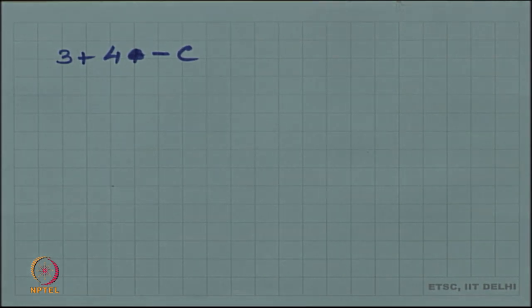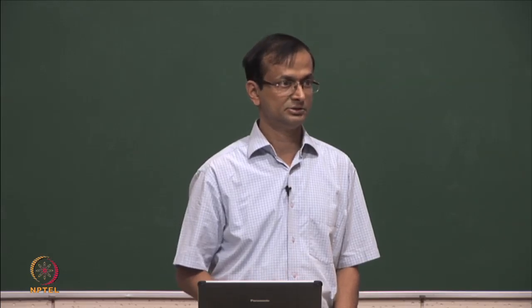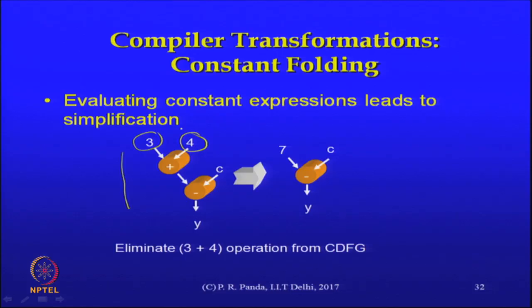Hopefully, it is obvious from the graph what kind of HDL statement it might have originated from. Anyway, all these behavioral statements need to be addressed in synthesis. We have to create the respective hardware. We illustrate the transformations through just a transformation on the internal representation, not necessarily either the source code or the hardware which is going to implement that source code, but this intermediate illustration should make it obvious.